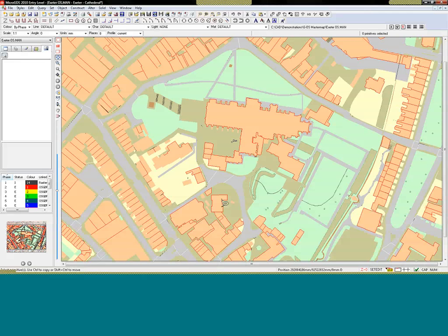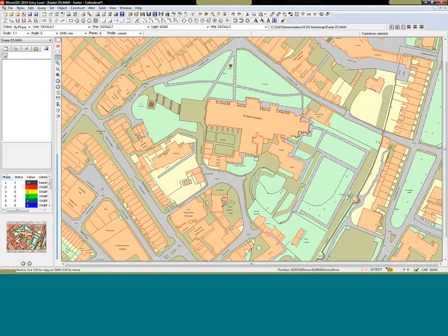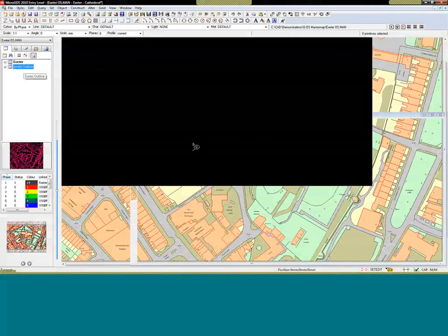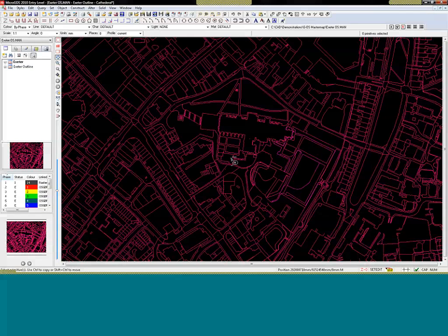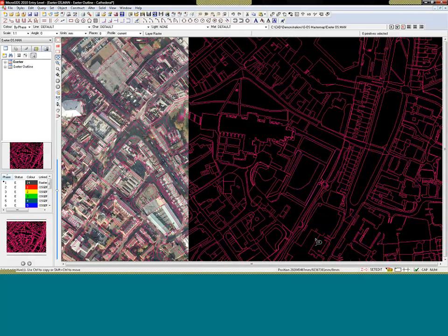And all of this information, all this style information you see here with the different colours and this text and other information that's attached to all of these elements of the project is exactly as it appears in the original master map data. You don't have to use it. If we go to our document organizer, you can turn off all of those styles and just display the line drawing if you prefer. And you can also obtain from the master map people the raster information that goes along with this and turn that on and layer it into your project as well. So you can imagine the opportunities for presentation that you've got here.